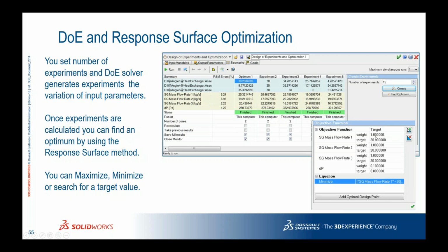The weight is the importance, the priority that we want to have on each flow rate. Also, we have a pressure drop with a target of 0. Let's say it's impossible to have 0, but it's to tend toward that kind of target. But the weight is 1/10 of the others because, of course, we know that this kind of target is not so realistic.